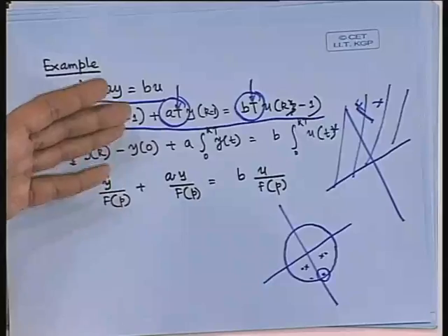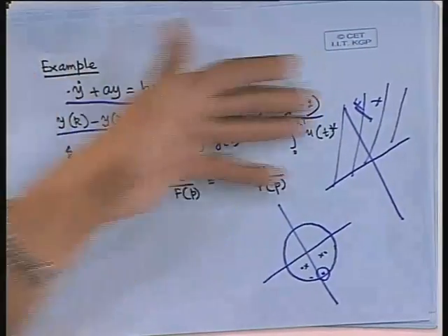After all, it is the steady state gain which is the reality. How you have got this parameterization is your problem. If your model shows a different steady state gain, you had it. Total control loop, everything will go haywire. Either your response will suffer or your stability margin will suffer. One of them will happen.